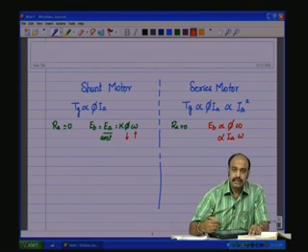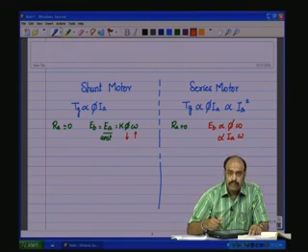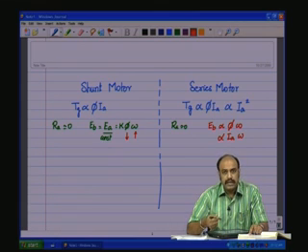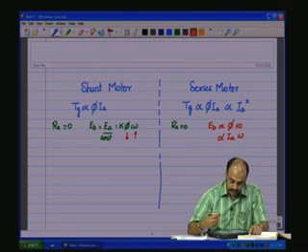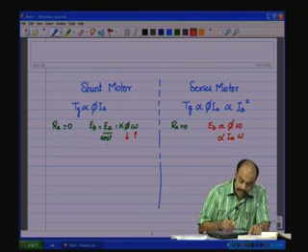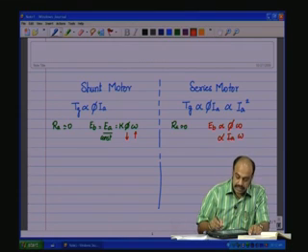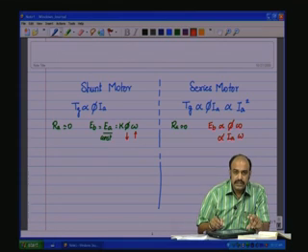But under loaded conditions, the torque will develop and then settle down at the operating point depending upon the load torque requirement. So, the runaway situation can occur in both the cases. Here, the runaway is the case when the field winding gets cut. In this case, under no load, when you switch on the armature voltage EA, under such conditions it can run away.